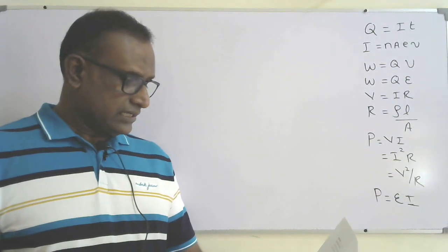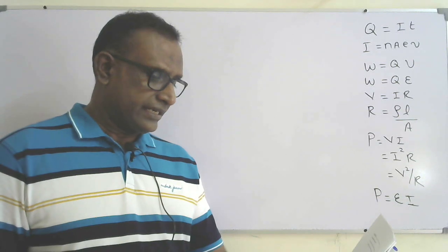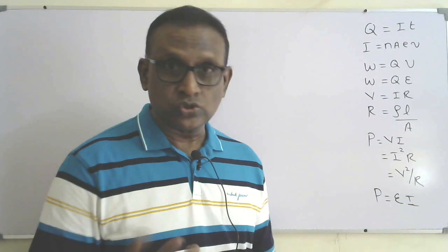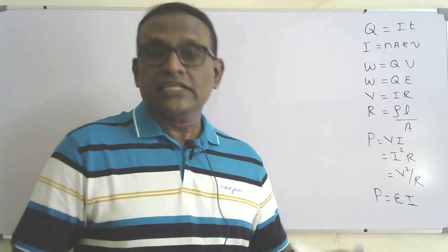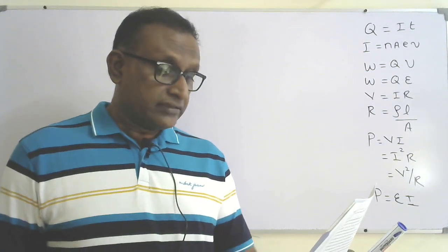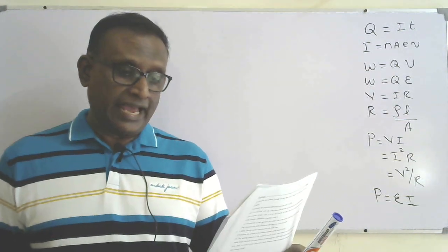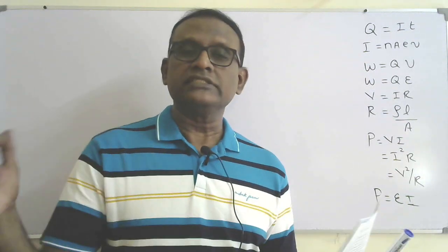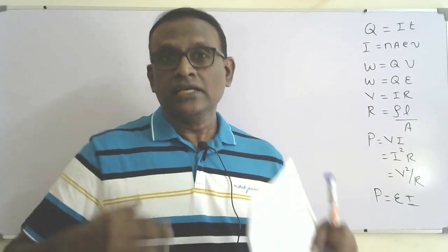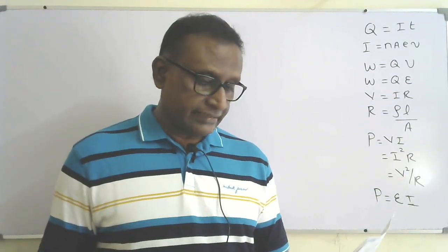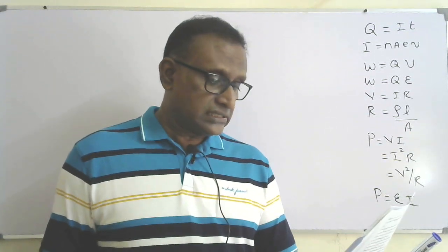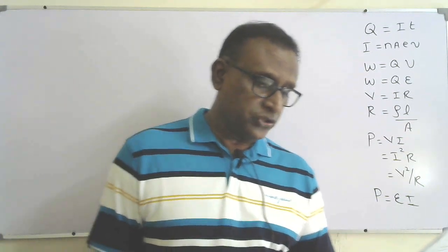Okay, third question. Energy transferred by a generator is 0.3 megajoule. That is 0.3 into 10 to the power 6 joule. That's energy transferred. Means that's energy generated by the electrical generator, when delivering a current of 2.5 ampere for 10 minutes. So the current flowing through the generator is 2.5 ampere and it's used for 10 minutes. And the total energy generated by the electrical generator during 10 minutes is 0.3 megajoule. How much charge passes through the generator during this time?